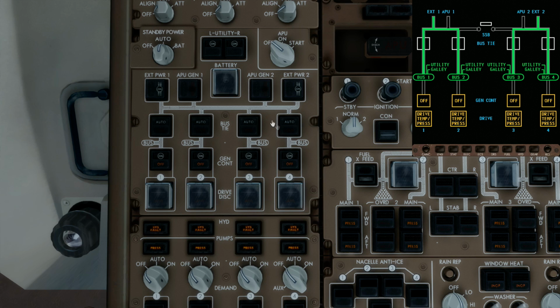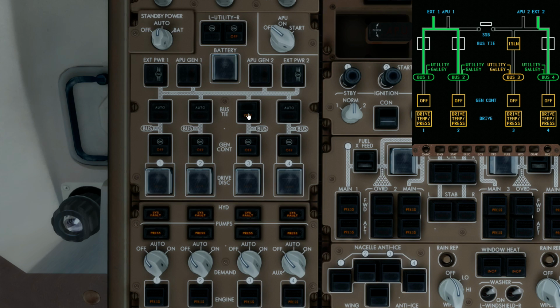The 3-position switch in the top left corner of the electrical panel controls the source of standby power. Auto is the normal position for this switch. Normally, AC bus 3 powers the main standby power bus. If, such as in our case right now, AC bus 3 is unpowered, then the ground service bus provides the power. So basically our ground power is feeding the ground service bus, which is powering the battery charger.